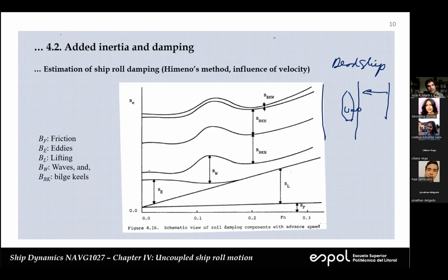If your ship is able to support that situation, once you start moving you can increase the damping coefficient and reduce the response. Second, you can change the heading so you don't receive waves from the beam anymore. So if you do not capsize in this situation, that means that in a regular situation, when you can move and select the angle of heading, you are going to be okay. That makes sense, right? And that's what IMO presented us.